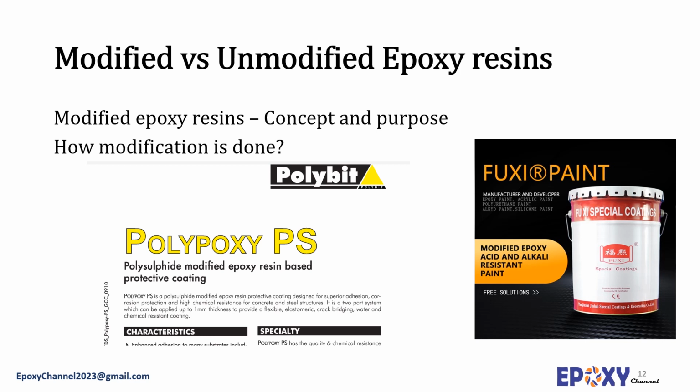Epoxy resins are often modified by structural changes, blending with other chemicals, using modifiers or using diluents to improve a certain property in the resins. They are often modified to enhance and maximize a property, for example, electrical, mechanical, adhesiveness, and chemical resistance properties. Epoxies have been modified in a variety of ways for different applications.